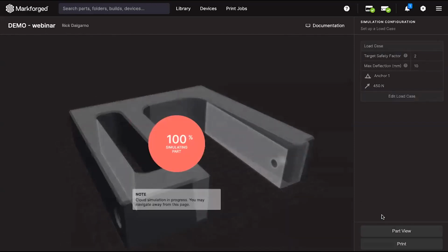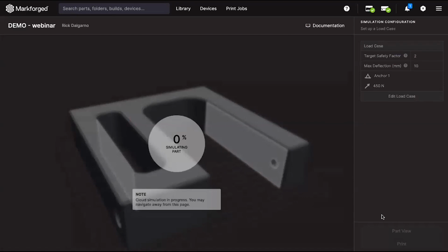And when I click optimize, the software will automatically generate alternate print configurations and run simulations in an attempt to find solutions that meet or exceed the strength and stiffness requirements while keeping print time and material usage to a minimum. Now, because it's running many simulations, the time to complete an optimization is longer than a single validation, typically between 20 minutes to about 2 hours on the high end. So I just press optimize, and I'm going to shift my attention to other tasks while it completes.